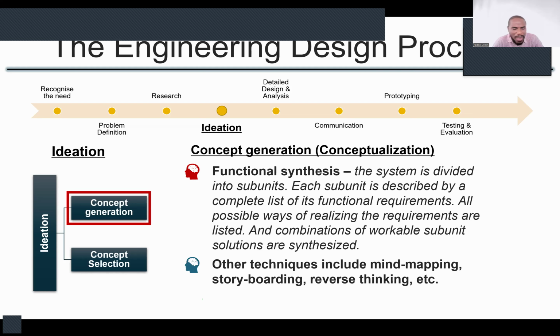You have various different moving parts, various things doing different issues. This morning, as I was coming, I was late because my car stopped. Okay, it started jerking. And what was the problem? The alternator was not charging the battery, and because it was not supplying the required power to all, vehicles now are very, very electrically inclined. Okay, the nozzles are controlled electrically. So once your electrical system has a problem, your vehicle will not function properly.